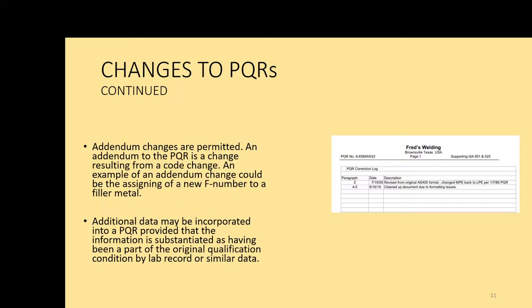Let's go to P5C materials. P5C materials are steels that were used in power piping, steam piping. 5C is one of the P numbers. There got to be so many of them, and the chemistry got so weird, that they split them out and made a whole other category.